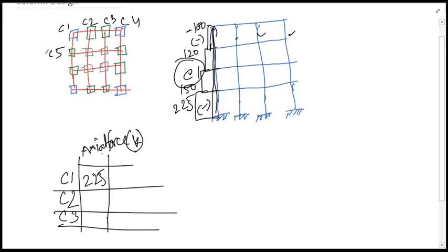And remember one thing, that for this C1 column you will be getting a similar value from the axial force diagram of this particular frame. So say for example, if this one is A and this one is 1, then if you draw this frame number 1, you will be getting this C1, and also if you draw this A frame, you will also be getting the C1, and you will obtain a similar value from these two frames.